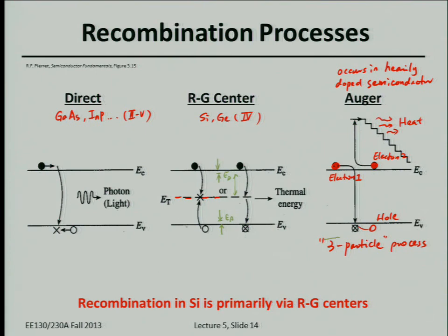So it's more easily than going from here to here. That's the normal thermal generation. You leave behind a hole here. With the trap state, you can trap an electron and then over time have an electron go up. So trap states actually are generally not desirable.